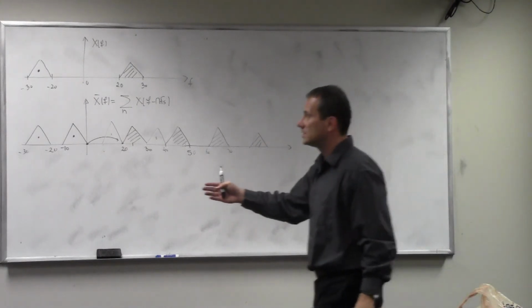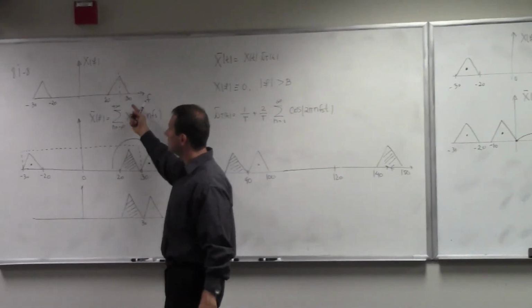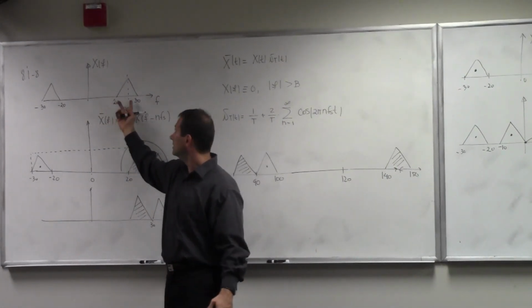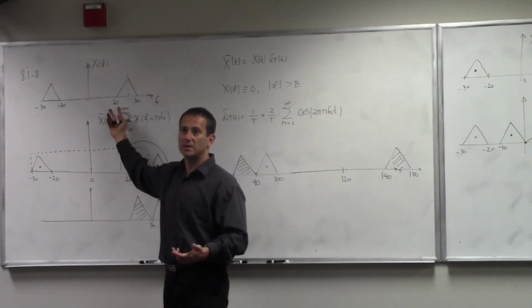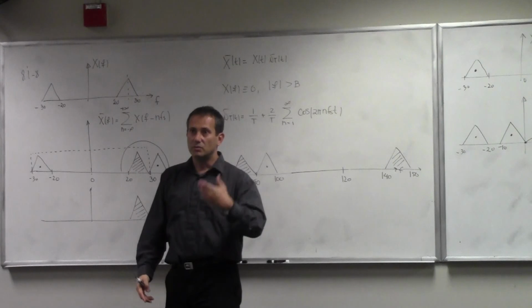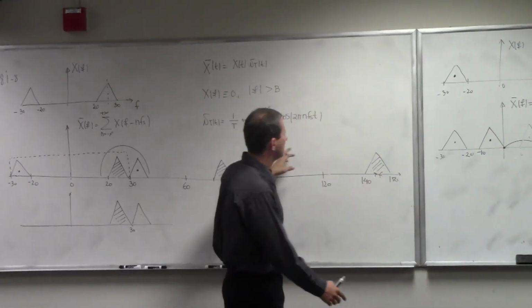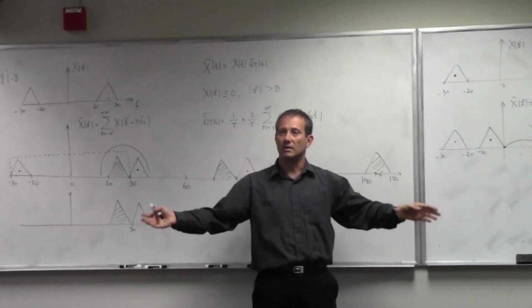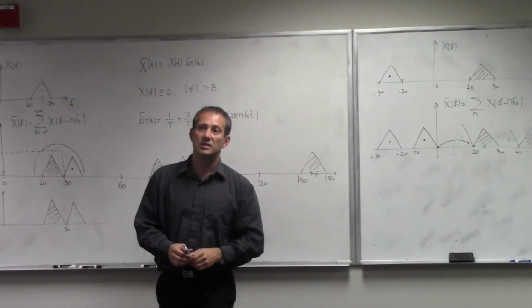But here we have some chance of being more economical than the Nyquist criteria. Really, this signal has a bandwidth of 10. It happens to be a bandpass signal. So I can do much more economically by doing what I had on the previous board: shift and multiply by cosine, multiply, shift around, and so on. And this is done a lot of the time.